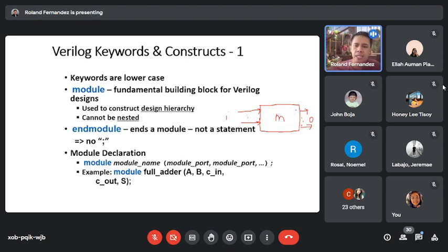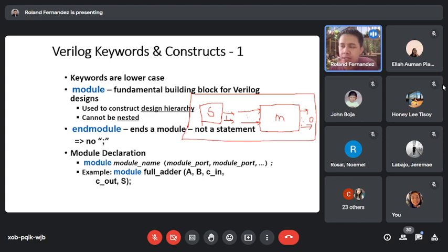In general, we create modules as well as simulators and we create the test bench. So for every module, we need to create a simulator that will produce values for our module. And also we create a test bench so that we can connect the two modules, the simulator and the module. We can connect them by means of instantiating. The lowest part of our code is the test bench. Also, the module is closed or ended via the endmodule command.